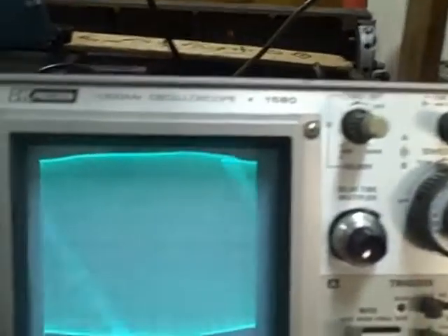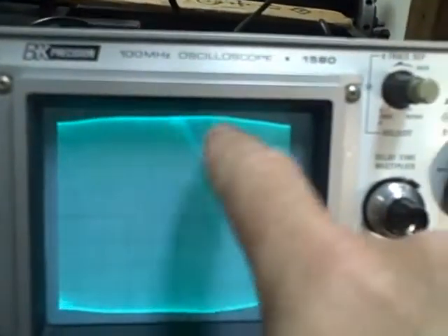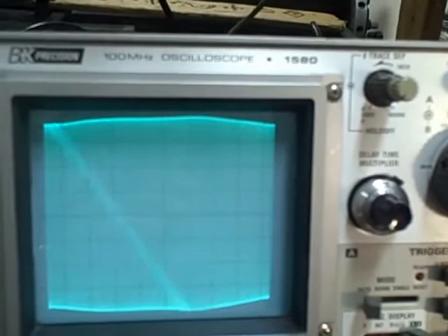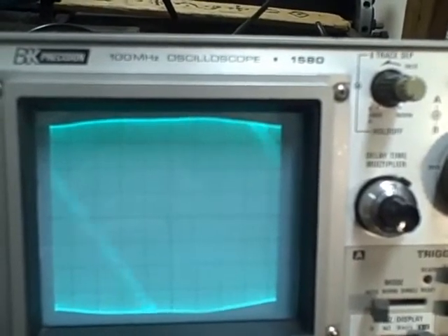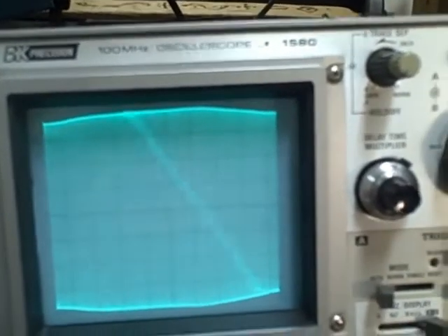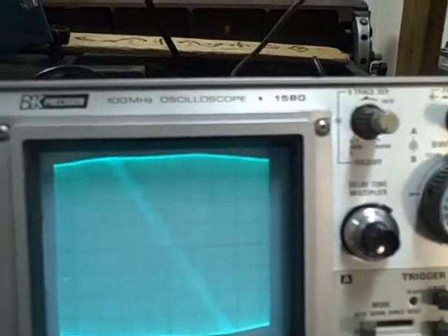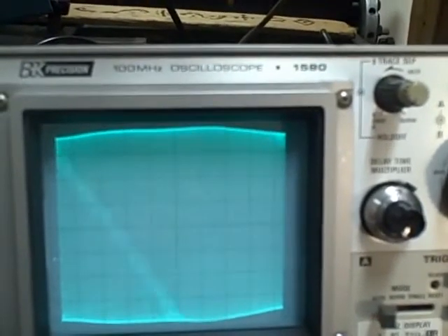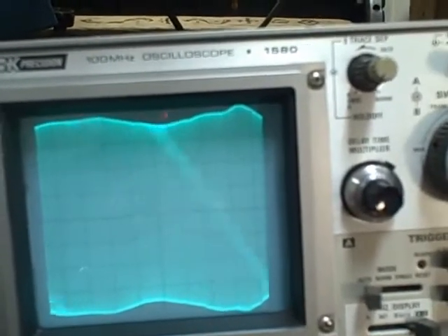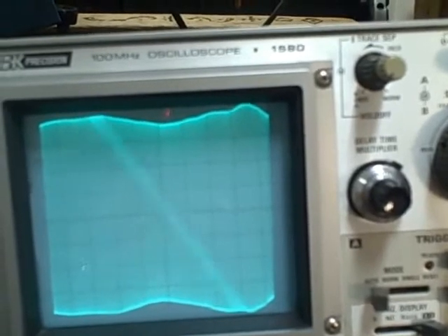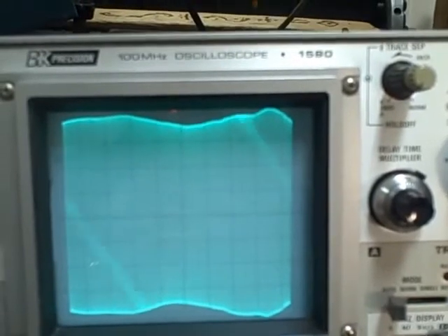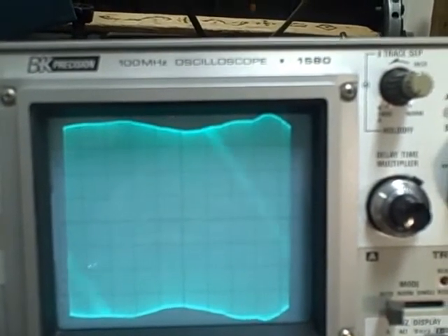Now if I was to bump the range up, we are now going up to 10 megacycles, and we see that we have a little fall off on each end, not much, a fraction of a division relative to the center, but still basically linear 0 to 10 megahertz. But now if I implement 0 to 20, I get some oddities here.